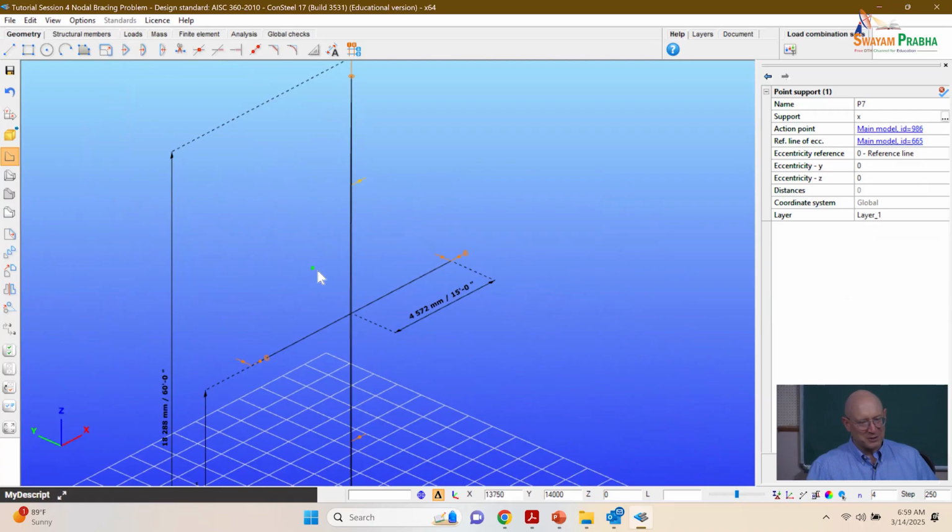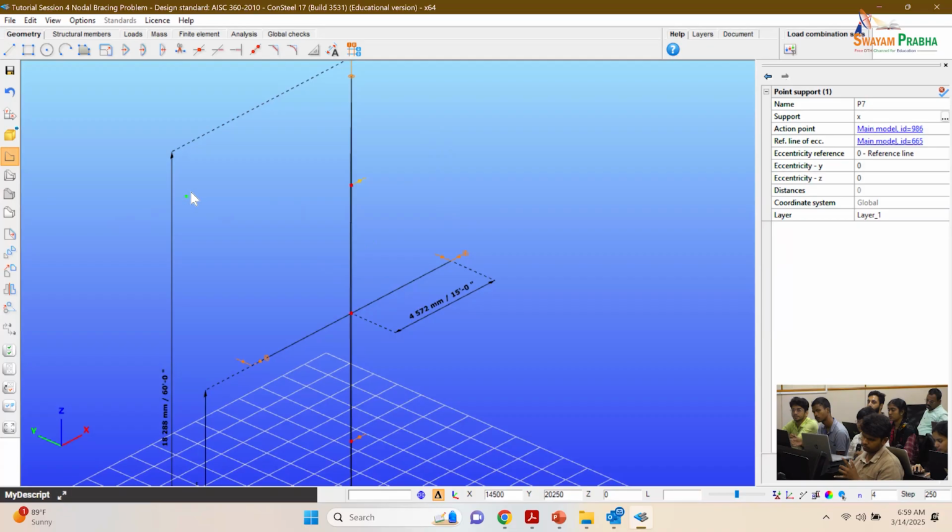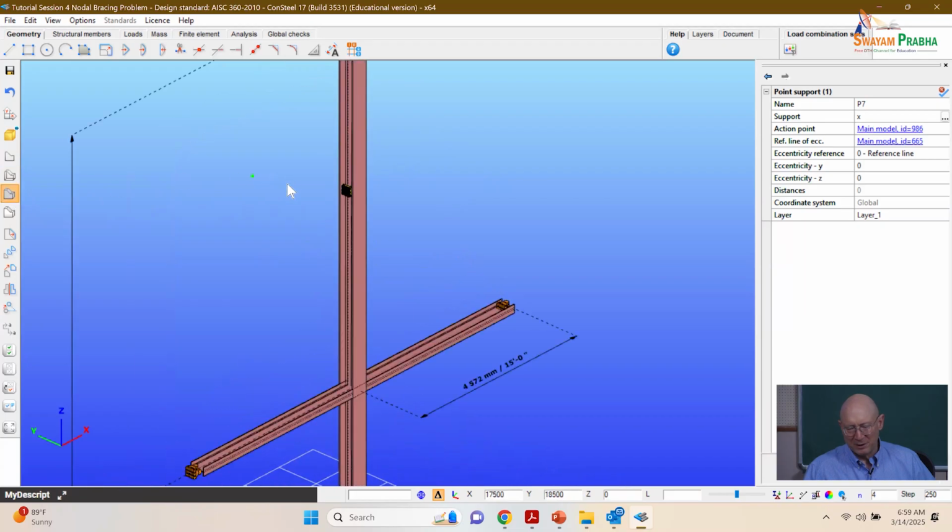So if you said what's the unbraced length LY for the column, what do you say it is? The whole thing is 60 feet. It's 15. 15, right? That's right. But if you say, what's the LZ? It's 30. 30 feet, right? Everybody good? Okay. So that's our situation here. We'll come back to this view again.